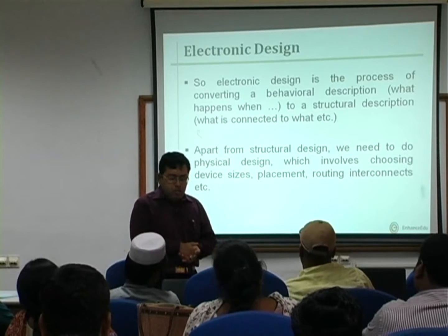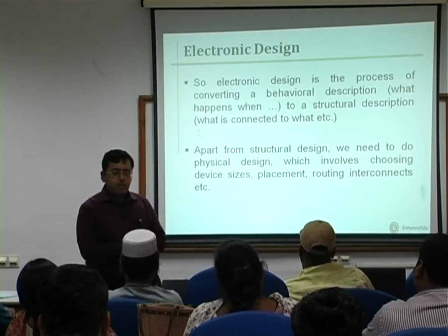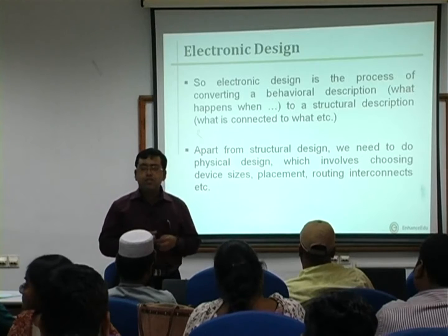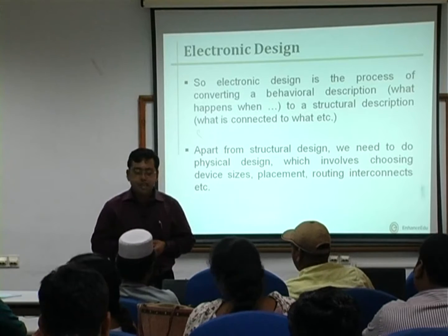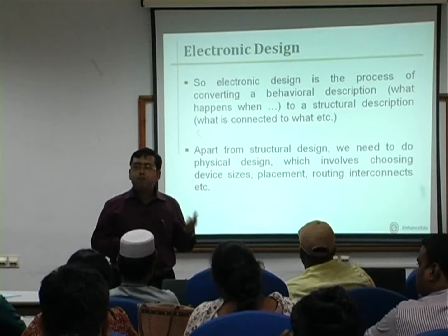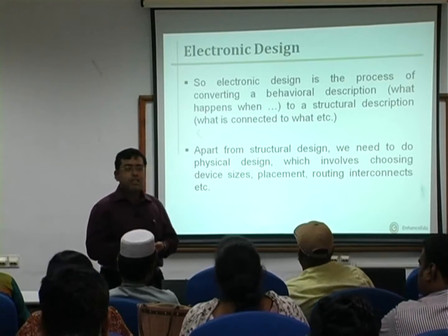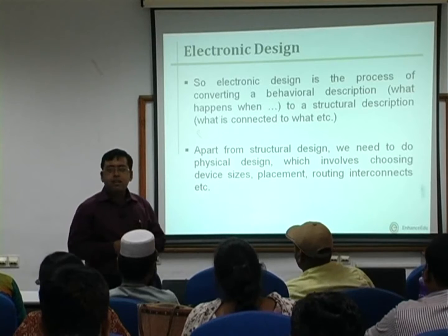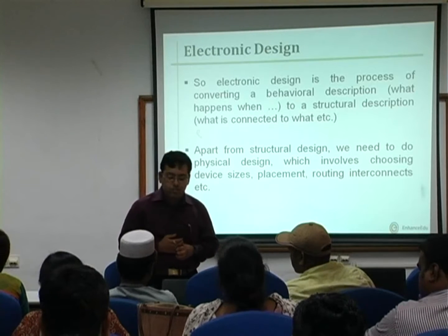This physical design again involves various steps which we shall see a couple of minutes later. That involves sizing the devices, then partitioning, floor planning, placement, routing, compaction, and various other steps which we shall see in due course.